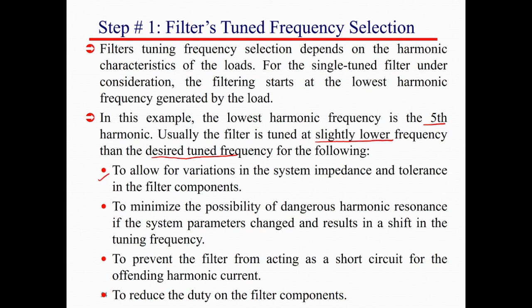The capacitor bank fuse could be blown due to aging and temperature, so the filter elements could vary. This minimizes the possibility of dangerous harmonic resonance if the system parameters change, which would result in a shift in the tuning frequency, and prevents the filter from acting as a short circuit for the offending harmonic current.